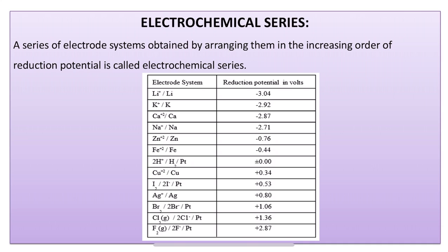The electrochemical series is a simple way of visualizing similar versus dissimilar metals. For roofers, you need to know what compatibility issues exist in regard to materials. So this is a chart which I am showing here, of common roofing metals. In most basic terms, metals that exist further apart from each other on this scale will react with a higher propensity for corrosion than ones that are close together.